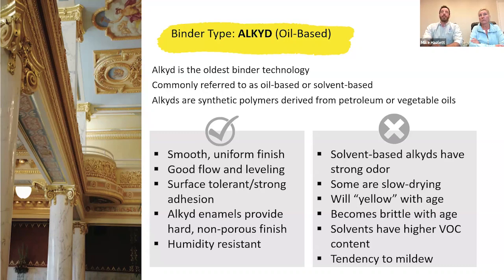And if we're in a multifamily or a condominium, I'm sure you don't want that lingering through the vents or coming down the hallway. Very slow drying. When I used to do color matches, I had to give myself a few extra hours when I'm color matching oil bases because it does take a longer time to dry and even longer than that to cure.